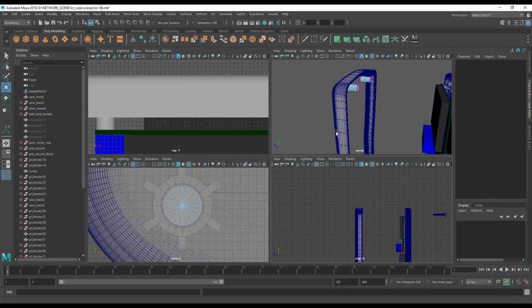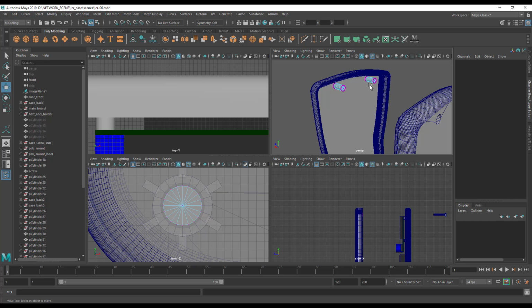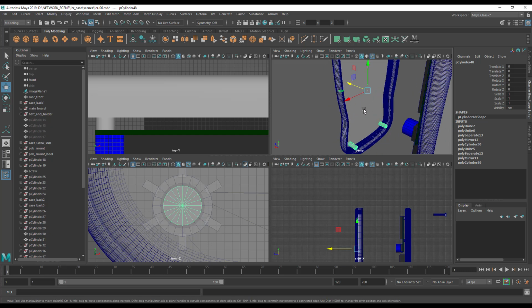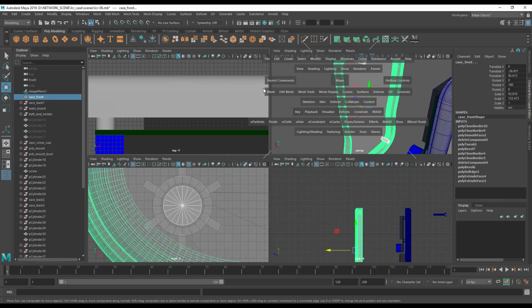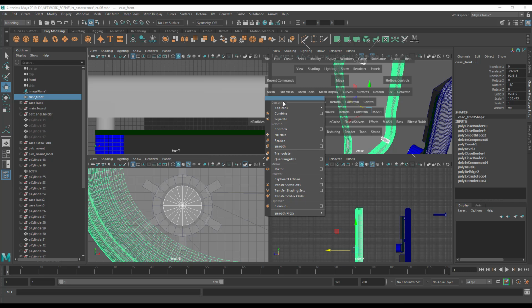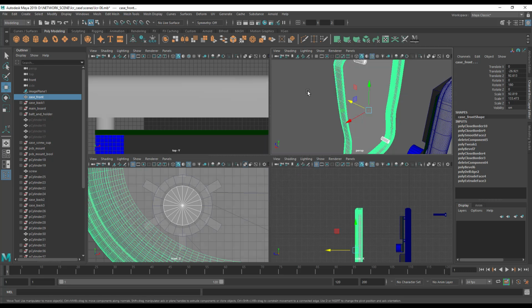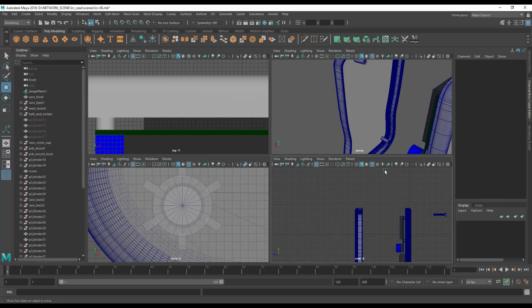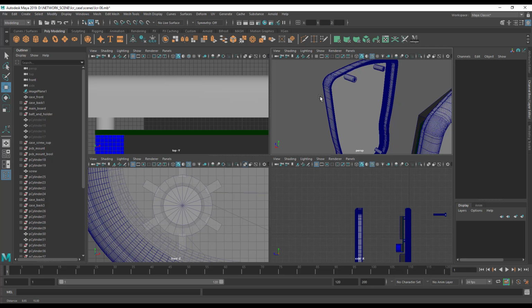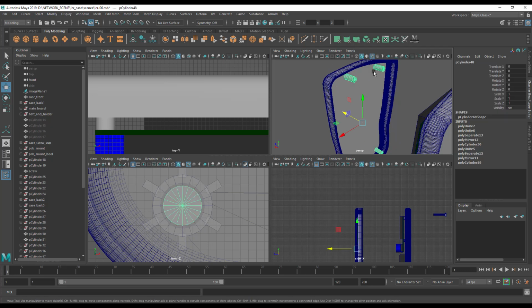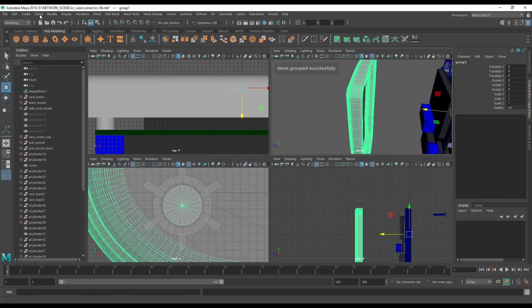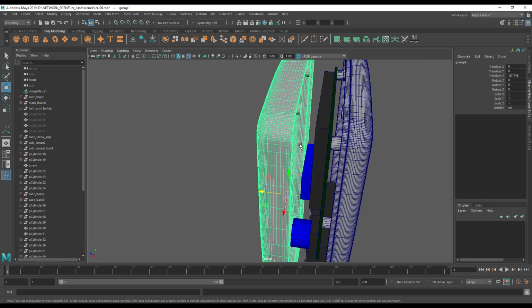Now, let's move the front and back of the case together and see if those line up. No reason that they shouldn't. So in order to do that, I'm going to select all of these. I'm going to select this, and I'm going to hit Mesh, Combine. Actually, I'll just group this. I won't combine it. So in order to do that, I'm just going to hit Control G. Oops, I lost my selection there for a second. Control and G, center the pivot, modify, center that pivot, and move these over here.